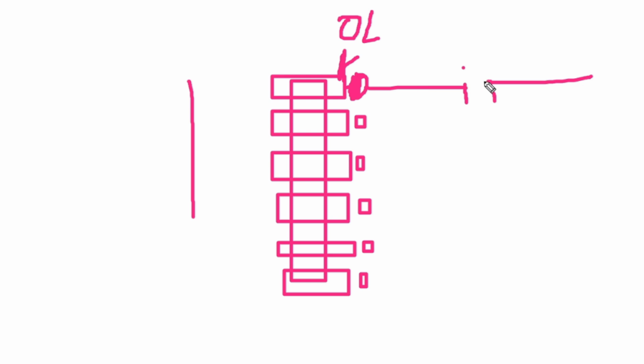This is the resistance place where you opened the resistance. If you measure this line here, you get a short, but this side is completely okay. So take a jumper from this side and put it here, solder on this side, because you already masked this print.